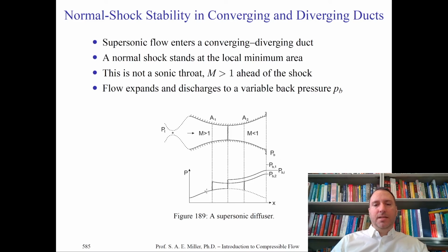And you can see, indeed, that if the shock wave is exactly at the sonic throat, it will result in the highest possible back pressure, which is good because we would, of course, recover that. If the shock wave is before or after the throat, then we would recover a lower static pressure in the back, which is less ideal.